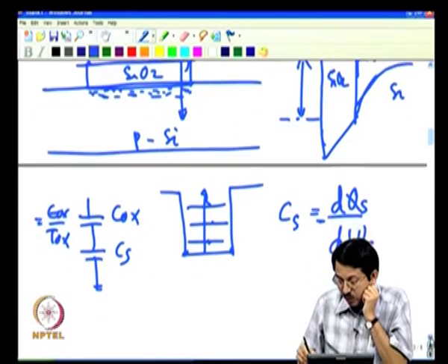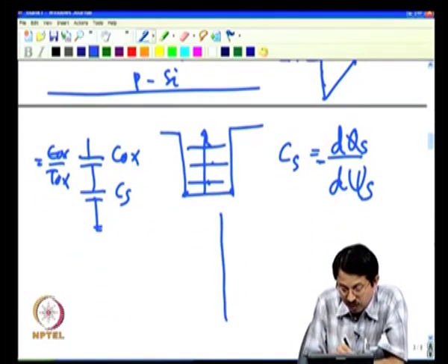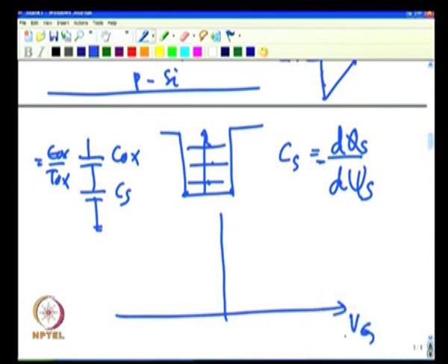If you are doing a CV measurement on a transistor, this is very important in the context of the MOS transistor. Your high frequency or low frequency, both, remember I said, will give you a curve which looks like this, wherein this maximum capacitance is C ox. Now in presence of channel quantization, charge quantization, your maximum capacitance in inversion will be degraded like this.